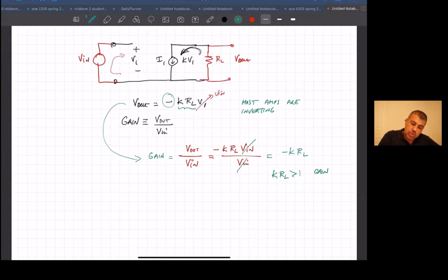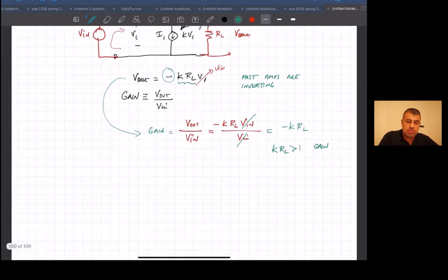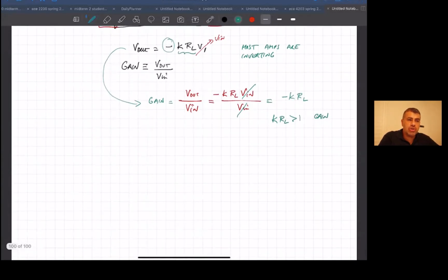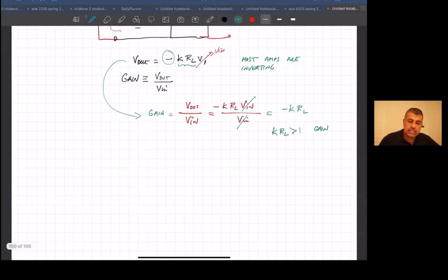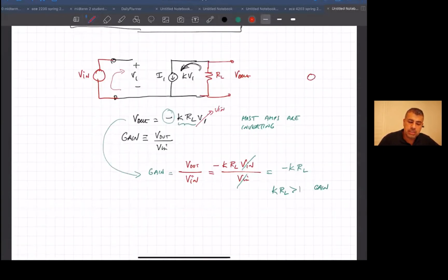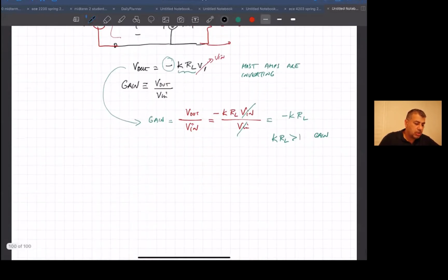So it's pretty clear. I think we're going to see this over and over again. There's a lot of different ways to get gain, but most of the transistors we'll see in the circuit are current sources into resistors, because that's how these transistors like to operate. You could do transistors driving other transistors as loads also, but the basic element is a current source driving some kind of high impedance load, which is either another current source or a resistor or something like that. But don't think about this for now. Okay, any questions about that so far?